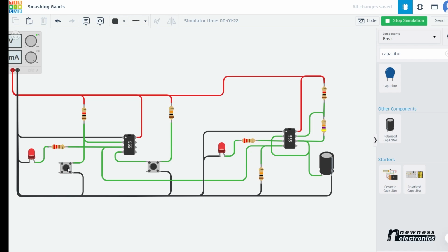All right, have you learned it? Another assignment I would like to give you is to make the frequency of this adjustable by putting a potentiometer in series with this resistor. Put a potentiometer in series with this resistor here. So we have that as an assignment. That will be all in this session.